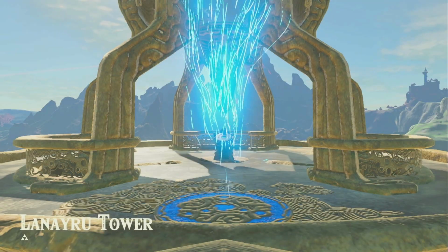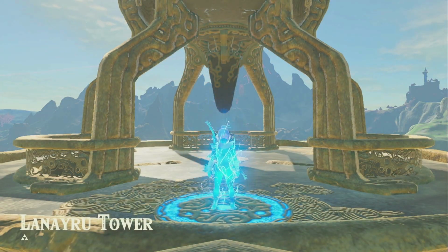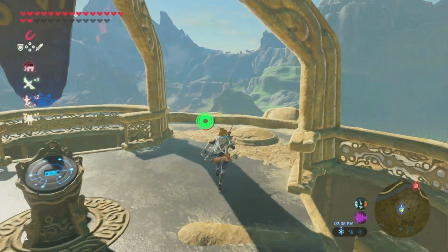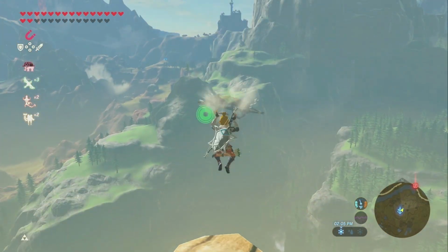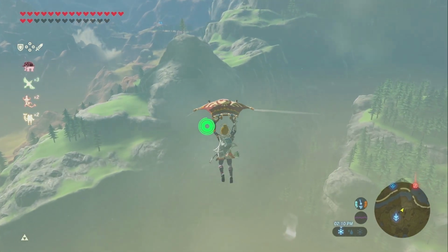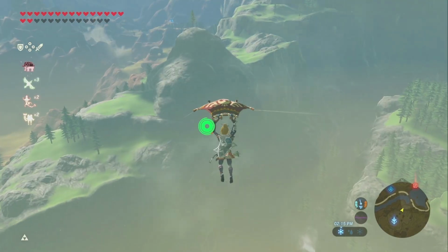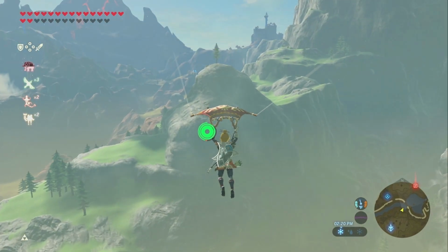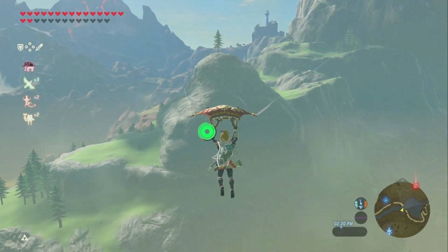Alright, another diagram. We like to see these, not a lot of reading. Alright, so a diagram here. The discharge pipe from the T&P relief valve should run continually downhill until it reaches its discharge location. A situation like this can cause the valve to malfunction.